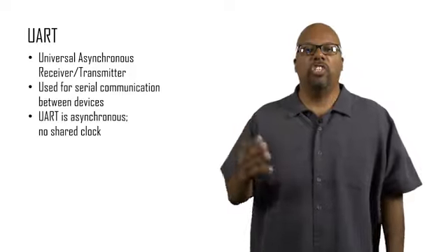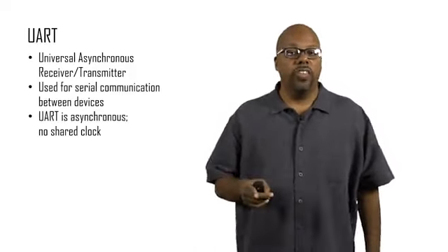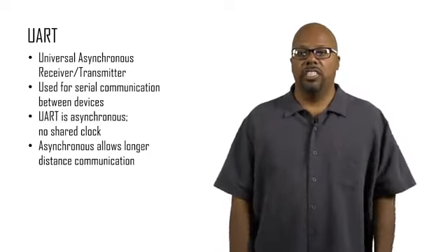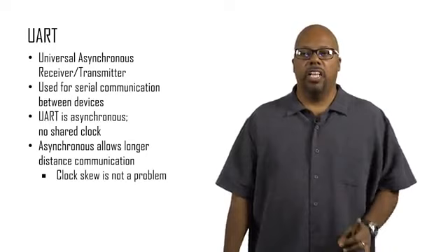So it's very hard. And that makes UART a nice thing, because UART is asynchronous, meaning it doesn't have a clock. It doesn't require a clock. So that's a good feature of UART. Now, as a result, UART is slower than a lot of other protocols, and synchronous protocols might be, but it has that advantage that it can work over very long distances because it doesn't require them to have the same clock. So you get the longer communication distance. Clock skew is not a problem.